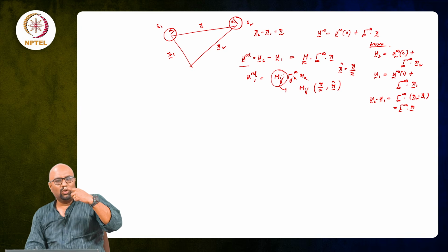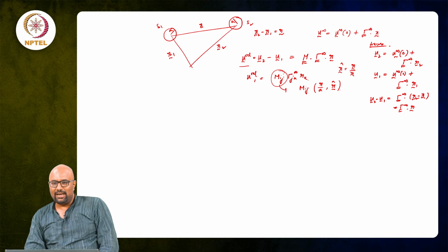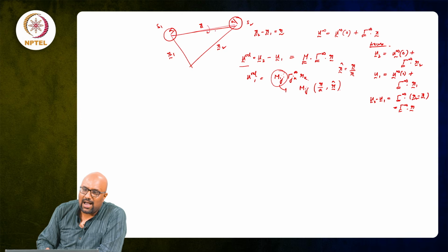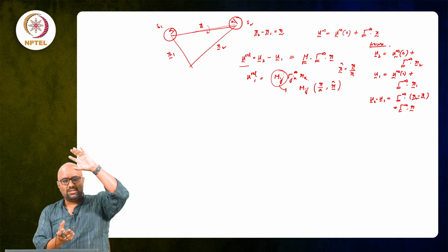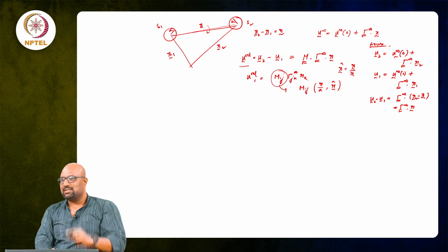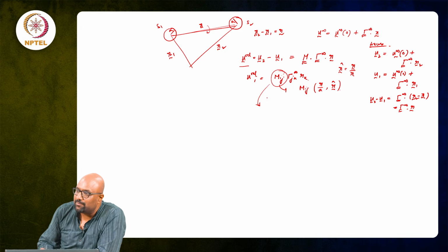It will depend on the unit vector for the separation vector and the length of the separation vector scaled by the sphere radius. Now, this geometry of these two spheres is axisymmetric. You consider the two spheres, there is a symmetry axis passing through the center of the two spheres. So, about the separation vector, the problem is axisymmetric. So, if it is axisymmetric, what would Mij be? What is an axisymmetric second order tensor?